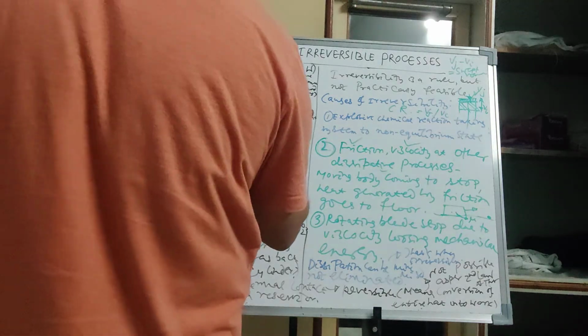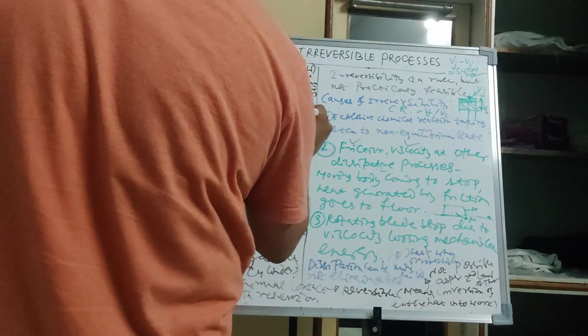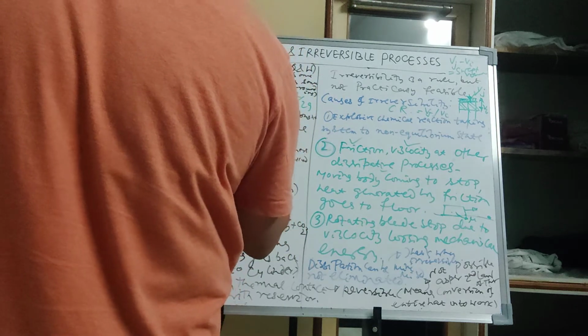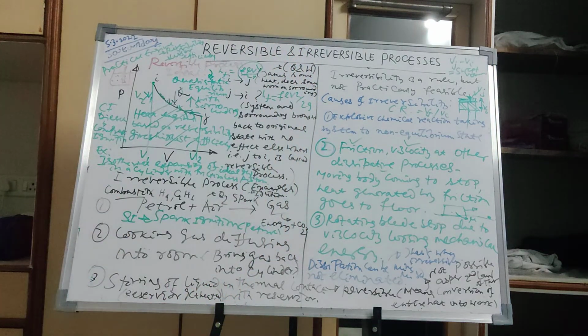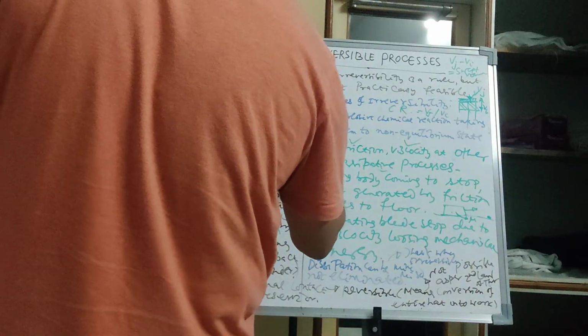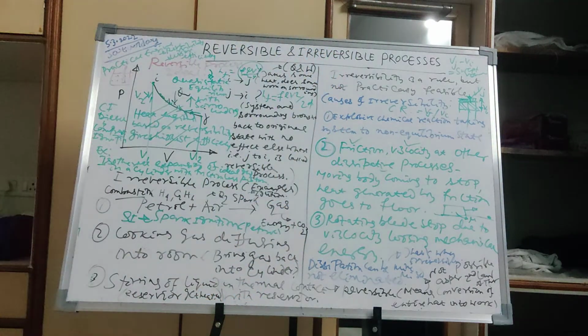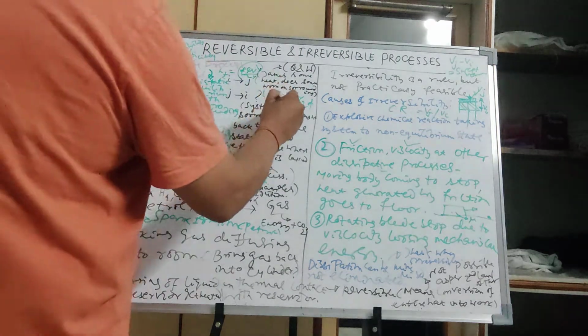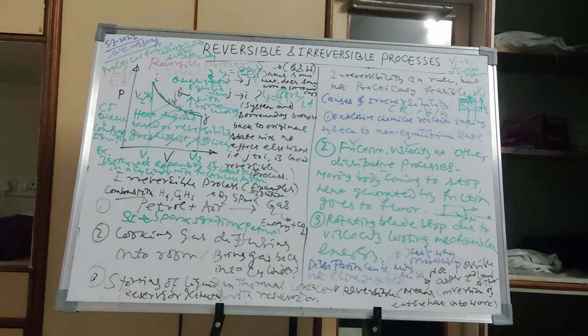We can brush up the formula. The longer the pipe, the larger the pressure loss. The higher the velocity in the pipe, the higher the pressure drop. The smaller the diameter, the more the pressure drop. This is called the coefficient of friction in the pipe, which depends on the viscosity of the fluid. The more viscous the fluid, the more the friction in the pipe.